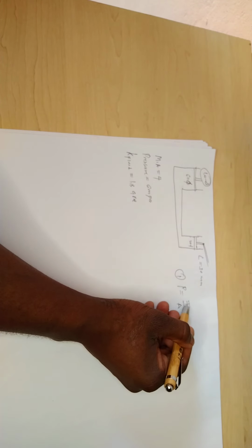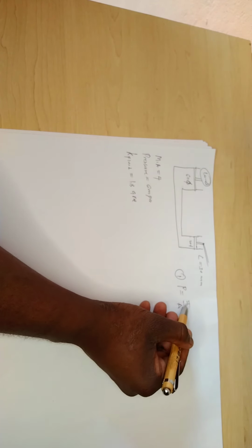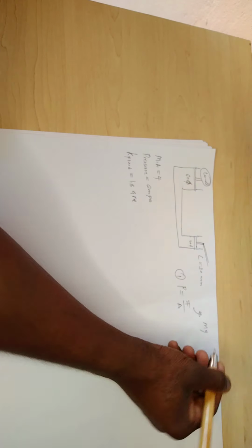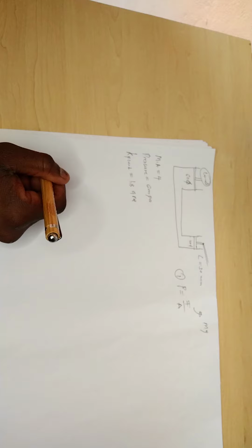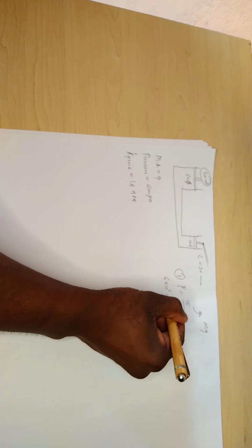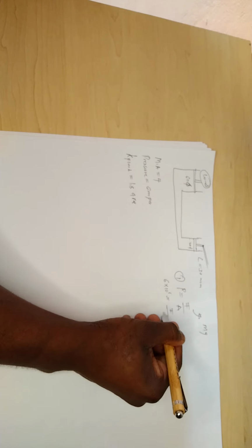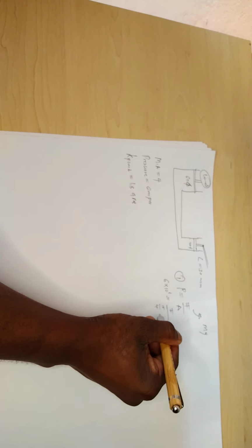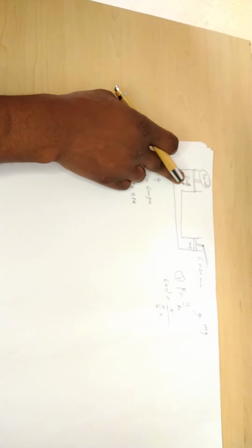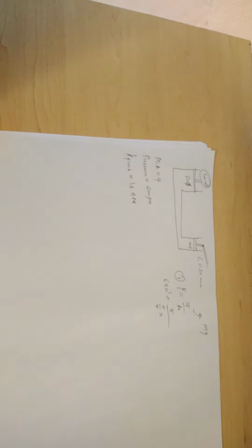If we find the force, we can get the mass, because we know that force is mass multiplied by gravity. So let's substitute. This is going to be 6 times 10 to the power 6 equals force over area. The area is pi over 4, and our D is going to be 0.06. You agree with me?